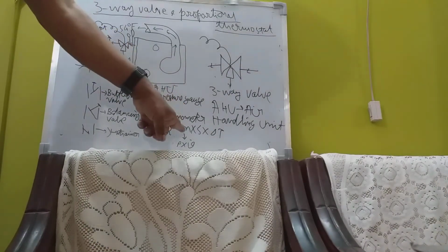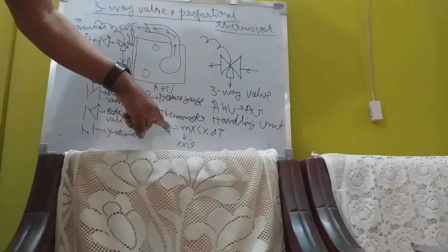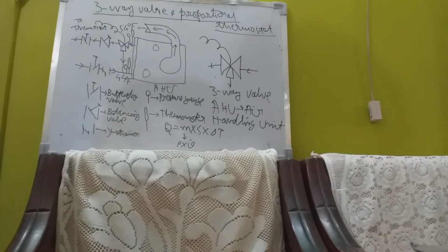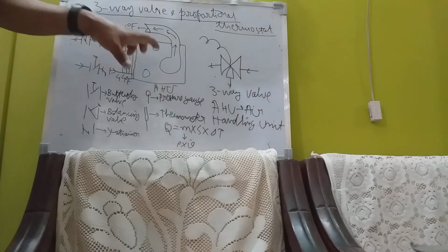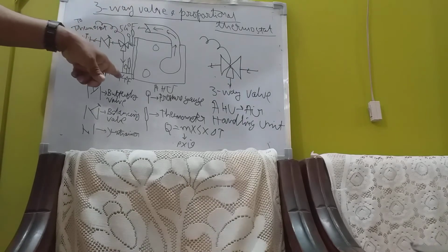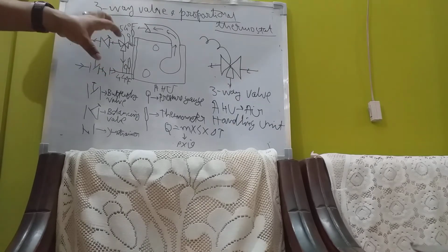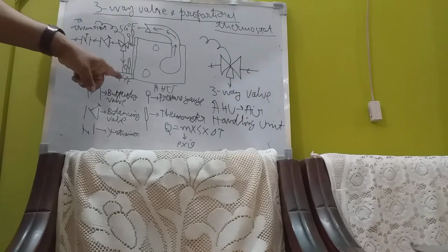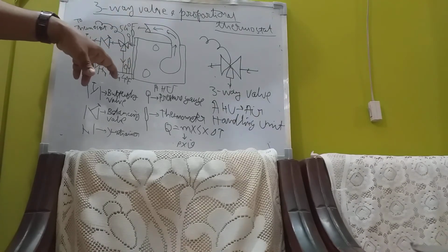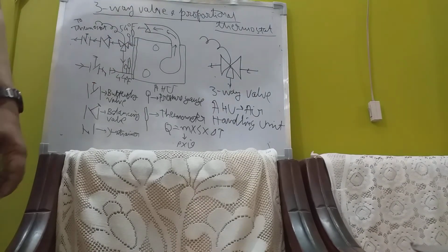When the mass decreases, as a result, since mass is directly proportional to Q, Q also falls. That means heat transfer falls, and the tonnage of the machine falls. But you remember, the temperature does not fall or rise, because I am controlling the chilled water flow. So temperature remains at 44 degrees Fahrenheit, which comes from the chilling machine. That we cannot change, because if we change the temperature here, it ultimately affects the temperature in the room.